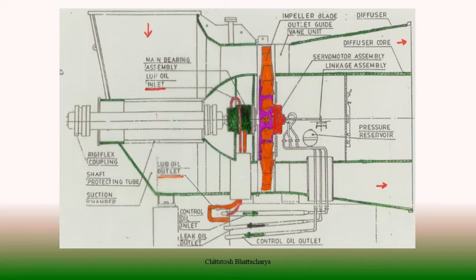In radial fans, impellers are fixed, but in AP-type fans, the impellers can be tilted with the axial blade pitch control arrangement. We can tilt them up to 60 degrees in 16 divisions, and that way we can control the quantity of gaseous fluid flow across the fan. So this is an additional feature along with damper control, inlet dampers and outlet dampers.